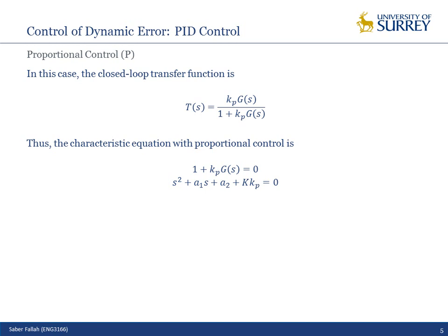And by changing the natural frequency of the system, we can change the rise time of the system. But you need to look at the lecture note. But the point is that if I improve the rise time, I will decrease the damping ratio of the system.